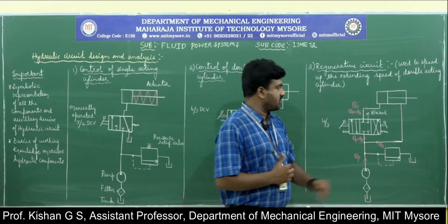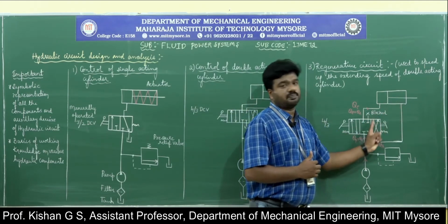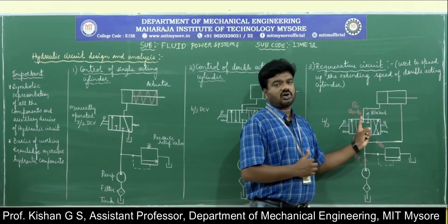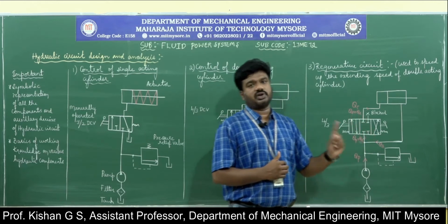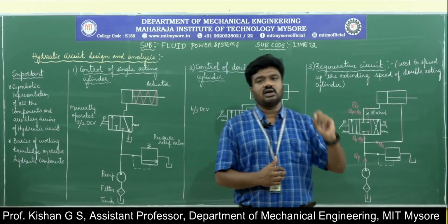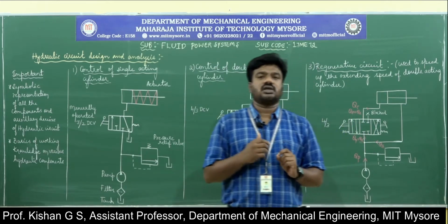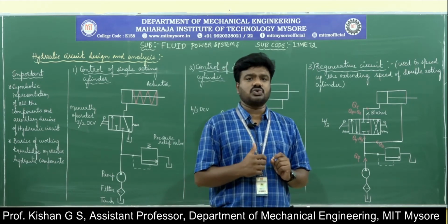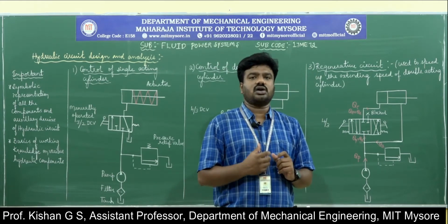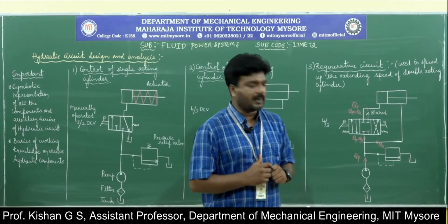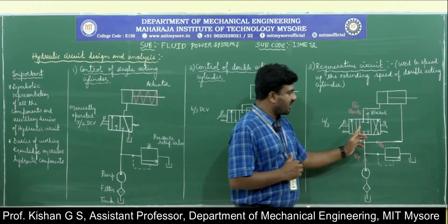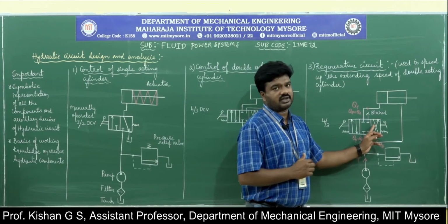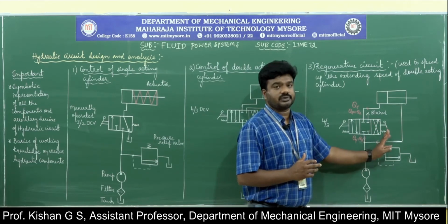In the second position, the system port B is blocked, which means you are not going to have any passages between system port B and the direction control valve, because the direction control valve will be blocked using a screw threaded nut or some such simple mechanism. So at that particular point of time there is no supply. Moving on to the third position.